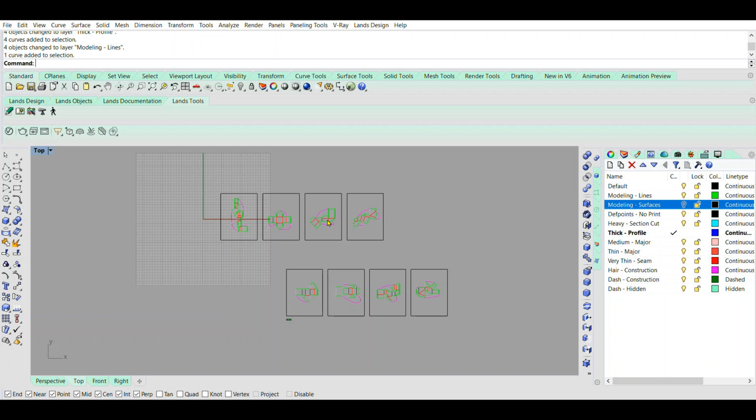Depending on if you are a Mac or PC user, the process of exporting from Rhino to Illustrator can be very fussy depending on which version of the software you're using. So just some tips if your file is not exporting or not opening. We'll talk about this a little bit more in Illustrator, but do a select all in Illustrator to make sure your lines aren't white. That way you make sure everything is being selected and that it's not invisible.